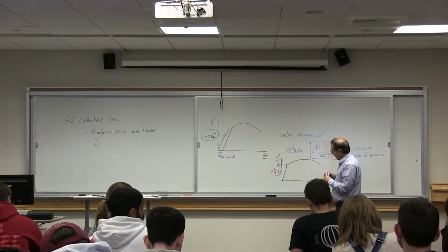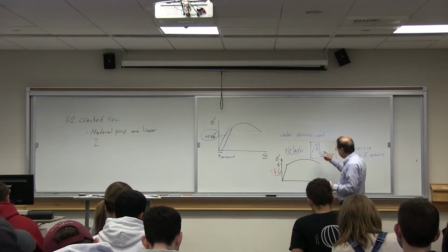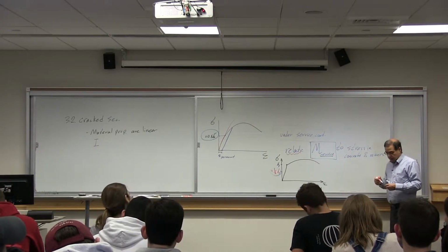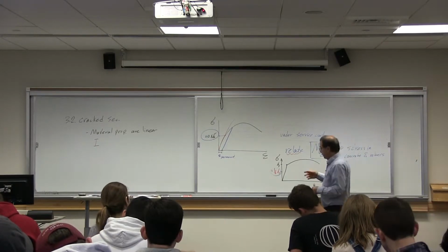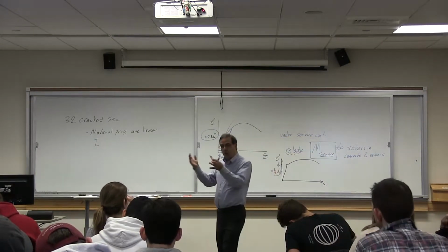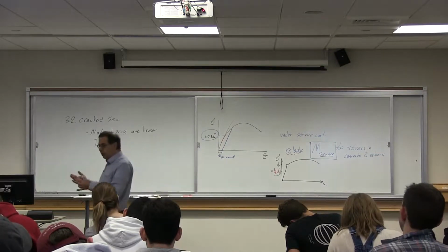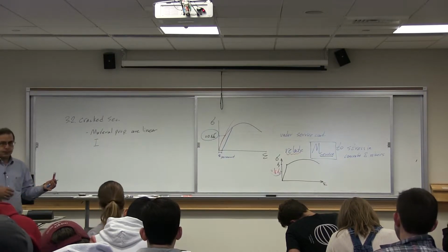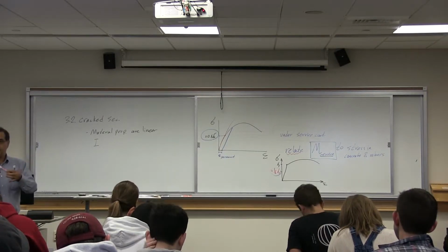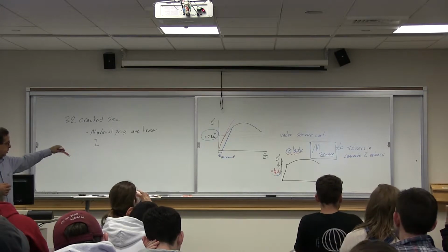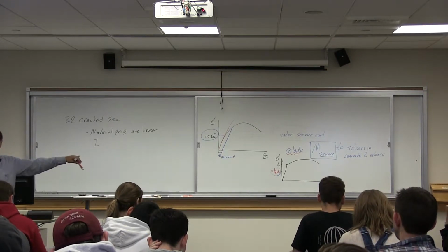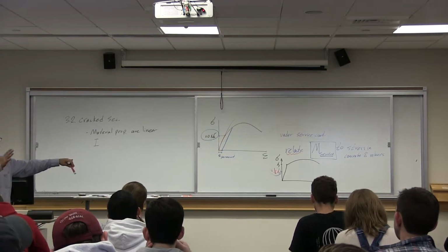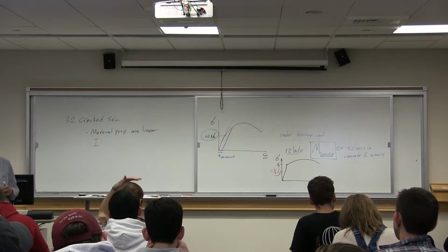We said we want to relate moment to a stress. It could be you have been given for a specific section a moment, and the question could be find the stress in rebar and concrete. It could be alternatively the stress limits in concrete and rebars are given, find the moment that would not generate stress more than the limited values.